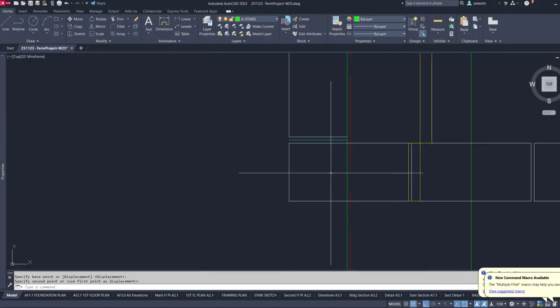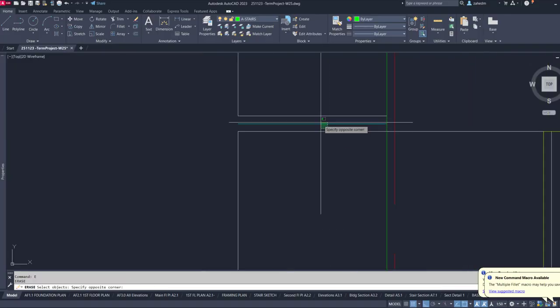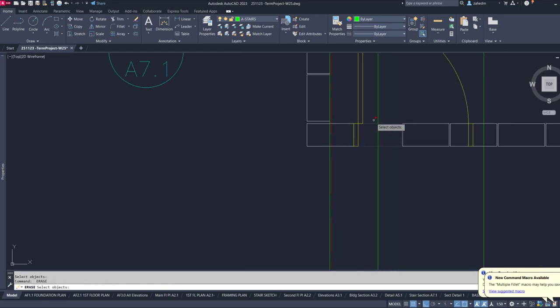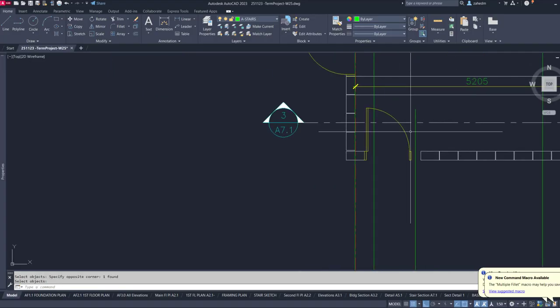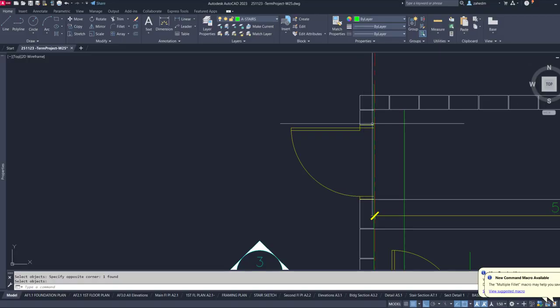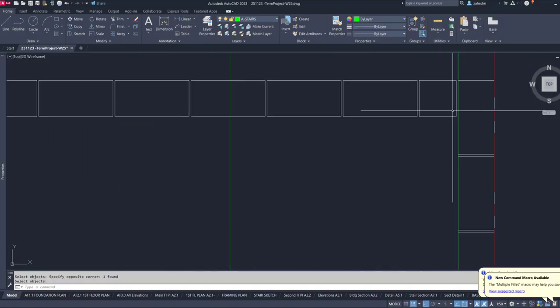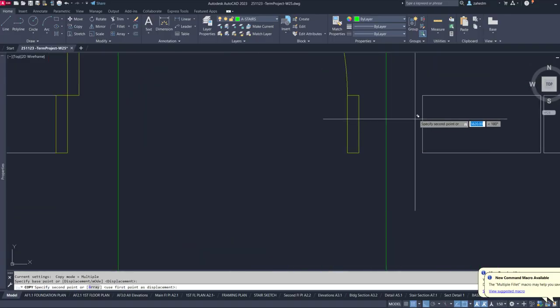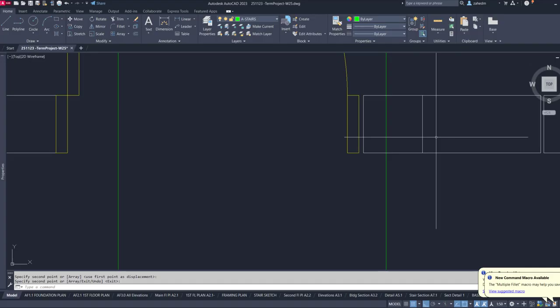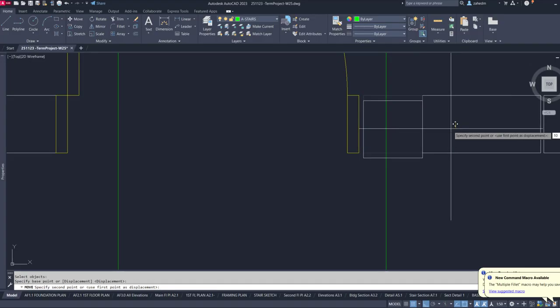Okay, so now they should be fine by having all these numbers, and then removing the extras, and then bringing a half a block. I'm going to use this half a block I made before, to this corner, and then I'm going to allow 10 millimeters for the mortar joints.